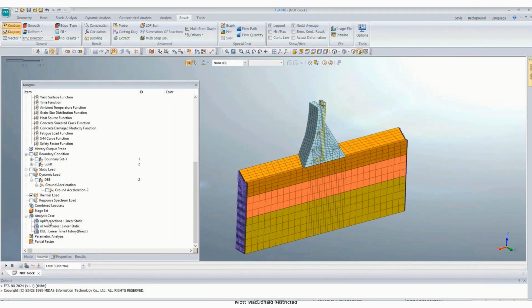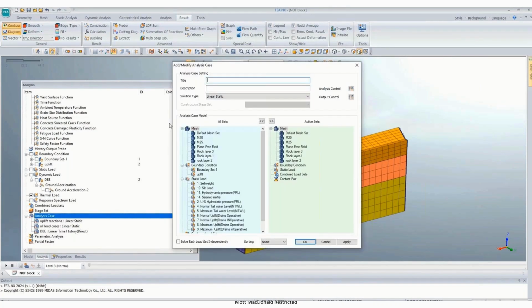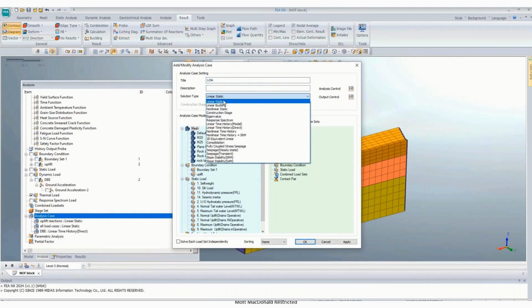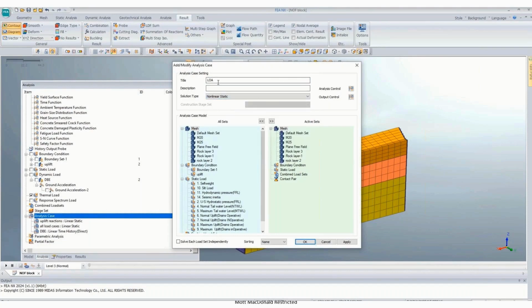For that, I'll consider load case B first. Let's say load B. I'll be having a non-linear analysis. We'll check the crack propagation also here. Static load I'll mention, say load case B. I'm not checking for load cases A, C, and F. Those are also static conditions with range. First, I'm just checking it for load case B.